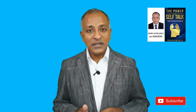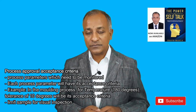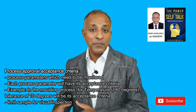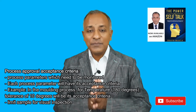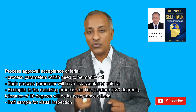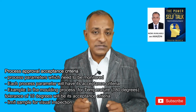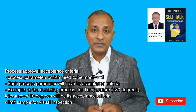Once the work instruction is ready, the next important thing is the acceptance criteria. Based on the control plan, it defines how to actually make the product based on certain parameters and guidelines. So in the acceptance criteria, the intent is that for different process parameters, which can be attribute or variable, some tolerances are specified. There are certain do's and don'ts, some master samples, so all those references come in the acceptance criteria so that it becomes easy to make the final product.